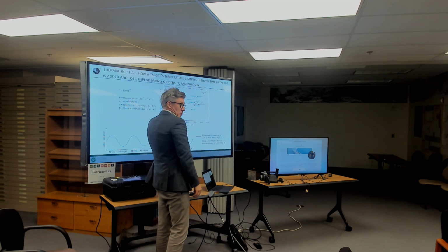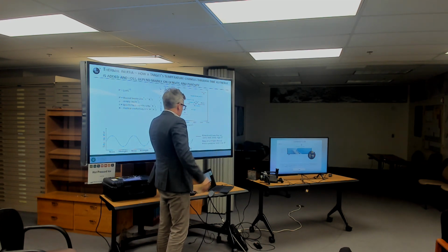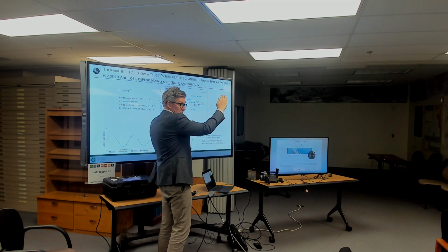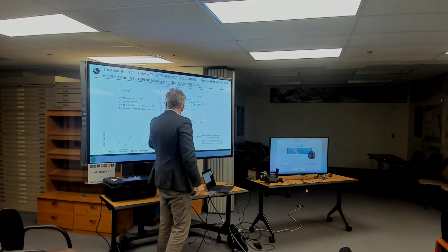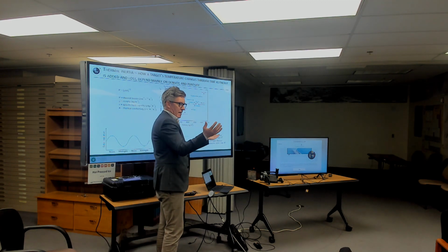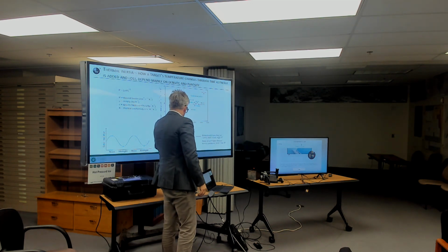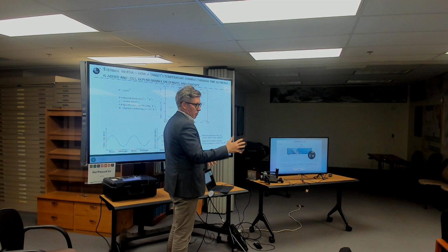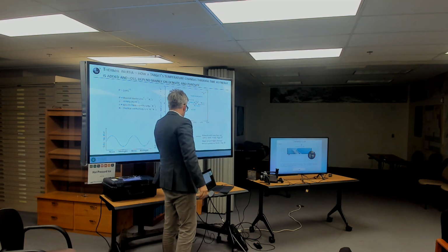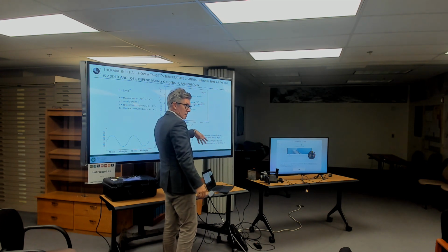The target will absorb that energy, and its own internal temperature will increase, and it will get hotter. And then as the sun goes from local noon and it starts falling, the cosine theta term starts to dominate again, and less energy will strike the surface. And the surface will radiate that energy, and therefore its temperature will fall. And then when the sun goes down, the surface is no longer receiving energy, and it just radiates energy into space until eventually it reaches a minimum temperature, which is the middle of the night, and then the whole cycle goes again. Right?